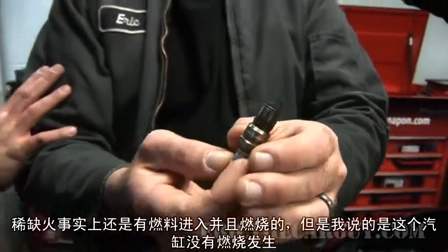But remember, with a lean misfire we're actually getting some fuel and a burn. I'm saying there is no burn in that cylinder, and that's kind of where I'm going. Maybe it's not going to be white. Do you know what I mean? Maybe, yeah. That's the theory behind the bright white plug, that combustion took place. But it's real hot. The fact that there's no combustion taking place and the spark plug is just firing, doing absolutely nothing in the cylinder, is probably what we're looking at.